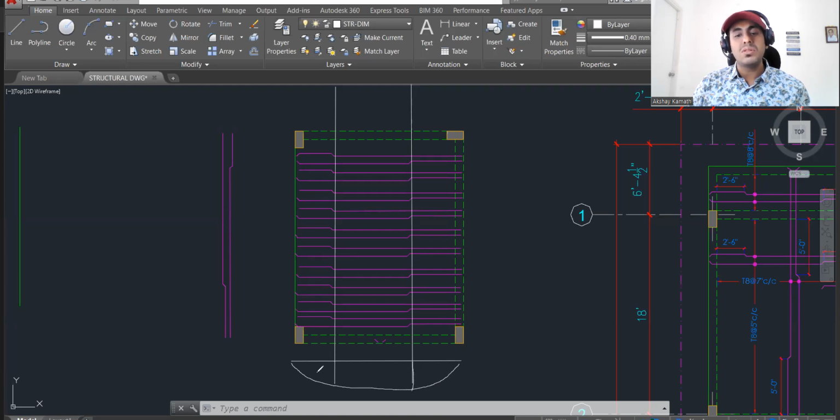Up to here, it was positive bending moment. Here, the bending moment was maximum. Here, it was minimum. You can see in this portion, the spacing, how much is it? What was given in the drawing? It was given 5 inches, right? So this is 5 inches, 5 inches, and so on. Now, in this portion and this portion, we know that you'll be having a negative bending